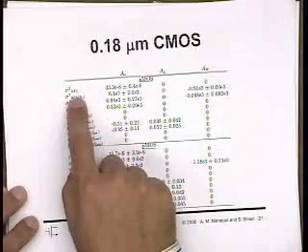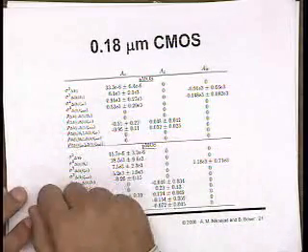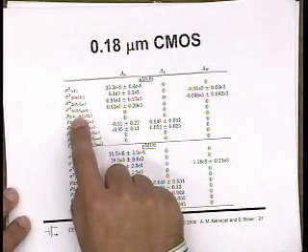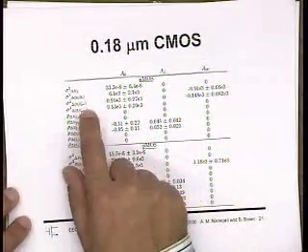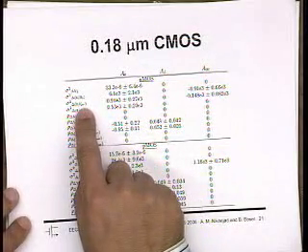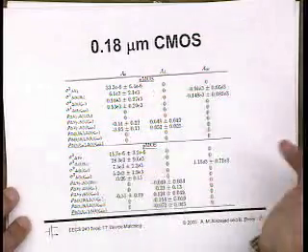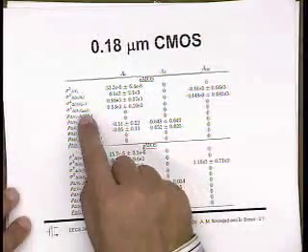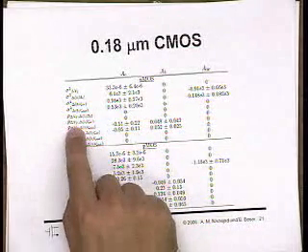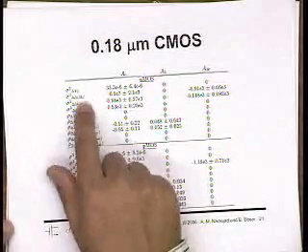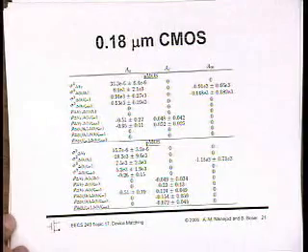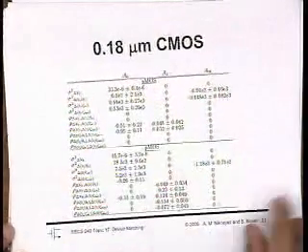So this is your VT mismatch, your beta mismatch. These are some coefficients that take into account some short channel effects, so velocity saturation mismatch. There's also a DIBL effect. This is a series resistance mismatch for our device. And in this particular paper, they lump the DIBL effect and some other effects into this velocity saturation mismatch coefficient. These rows are correlations between coefficients, and usually you're going to just neglect correlations, right? Make life easier. So there's NMOS data, PMOS data.